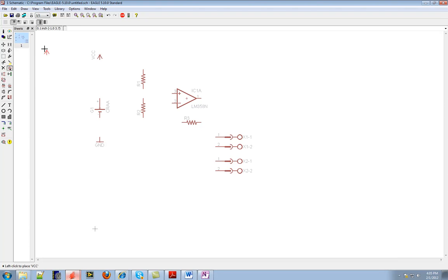Every circuit needs to have this node labeled. These are going to be nodes. Okay, so now I've got all my parts in here. Now I am ready to connect them with a net. So a net, the net tool is down here on the left. Drag it over. And when I do that, I'm ready to create more or less wires indicating what's connected to what.